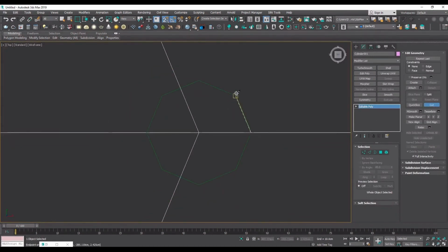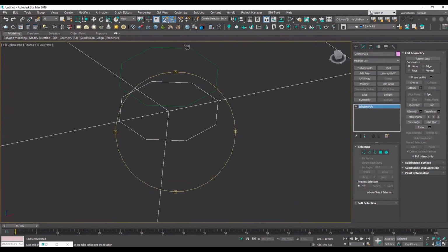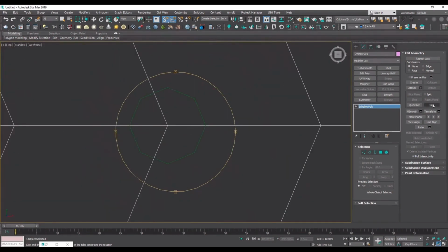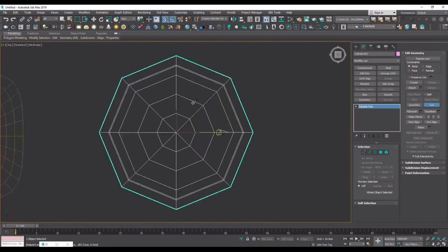So you have to return to your model now and pick up the cut command, and based on the octagon verts, based on our 8-sided shape, you must cut the geometry and basically copy the shape of that onto your hard surface model. So basically I'm just using this n-gon shape as a base, or better say as a reference, to be able to cut this exact shape onto our mesh.